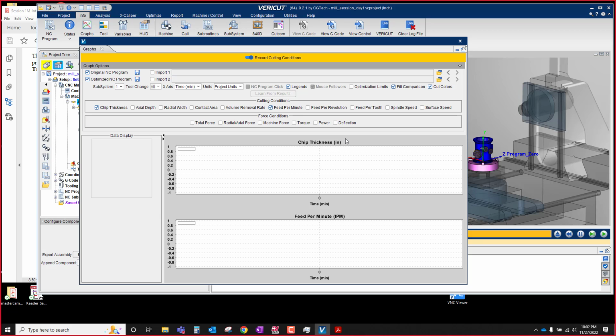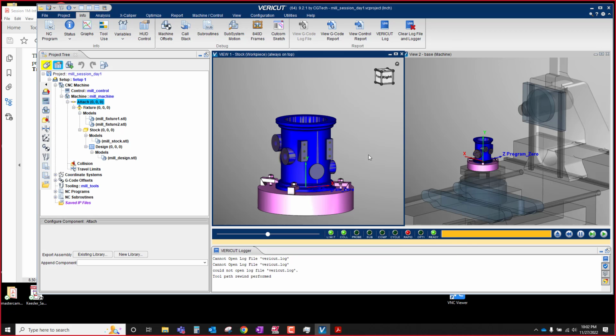So if you're cutting 17-4 PH at a certain hardness, you can either ask them to do a study and develop one of those files, or if they've already got it, you can just purchase the file and record all that stuff in Vericut as it's cutting, and you can actually set limits. So you can say, hey, if my programming parameters exceed the force characteristics of this material, go ahead and modify my G-code. And it actually creates a separate modified G-code file, right?